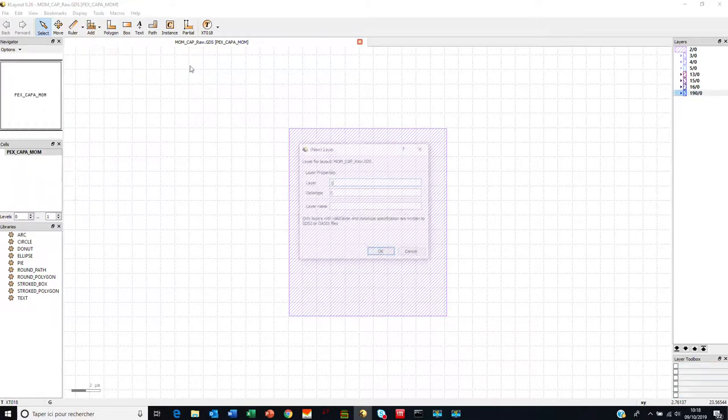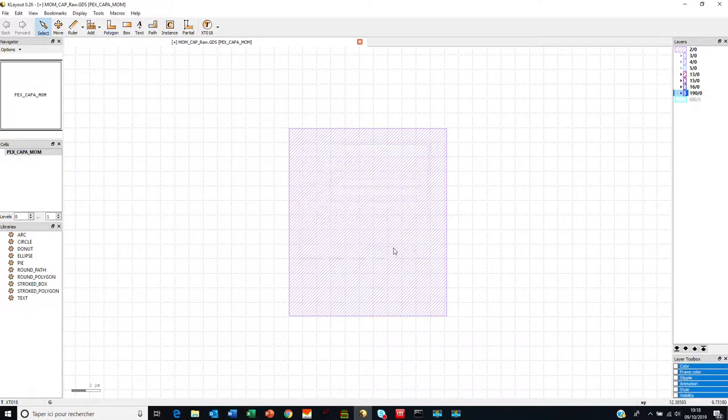It's just to create a new layer, and let's say we call it layer 600. The PWell layer is just the Boolean inversion of the NWell layer. The problem is that to perform a Boolean operation, we have to operate between two layers to define in which area this PWell will extend.